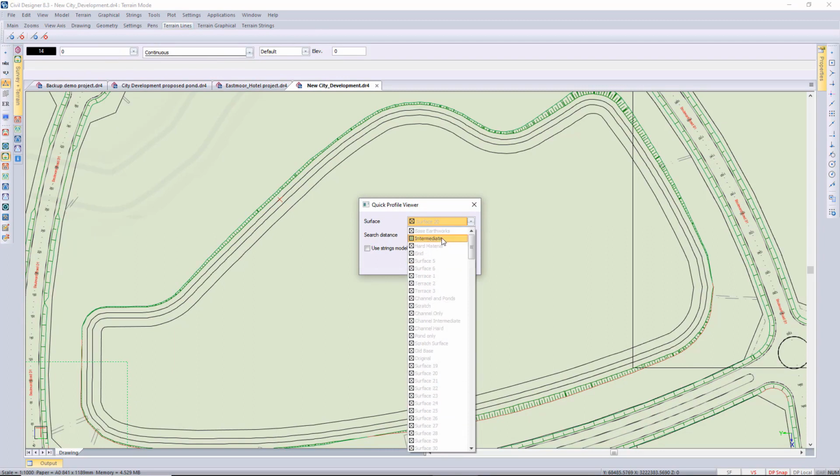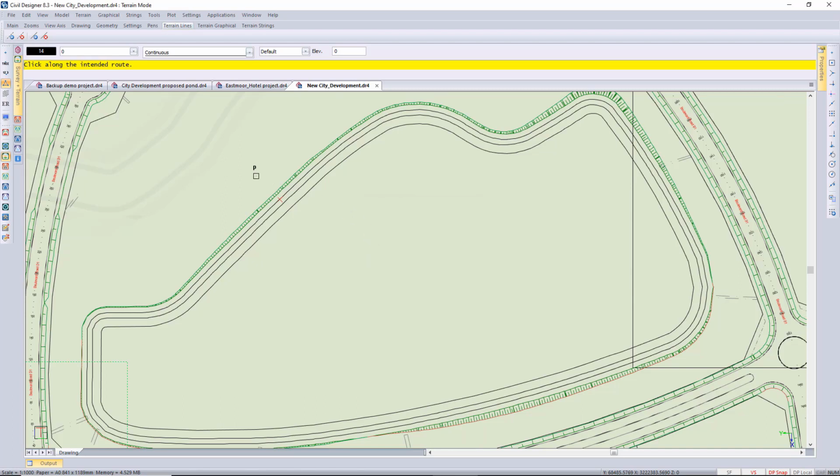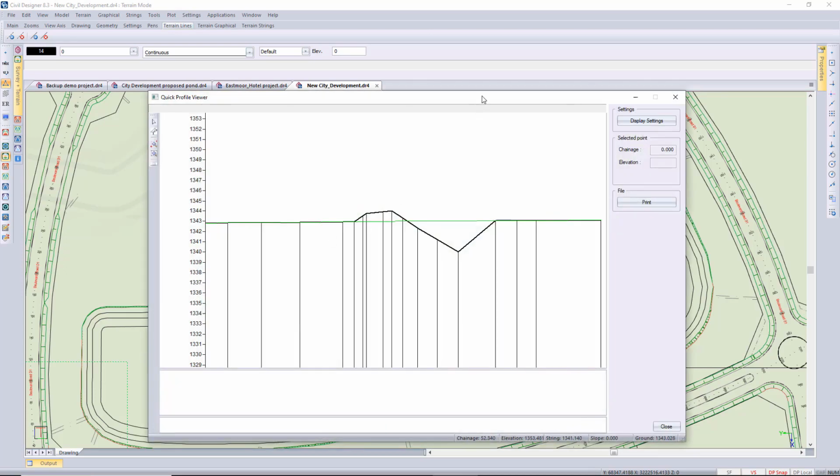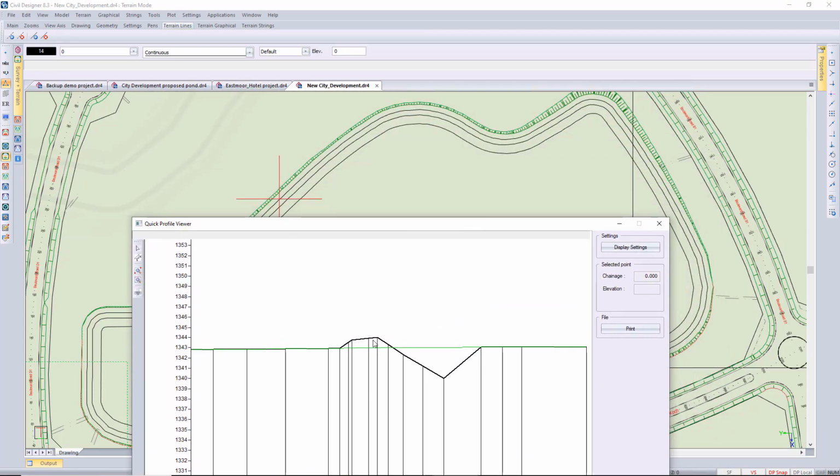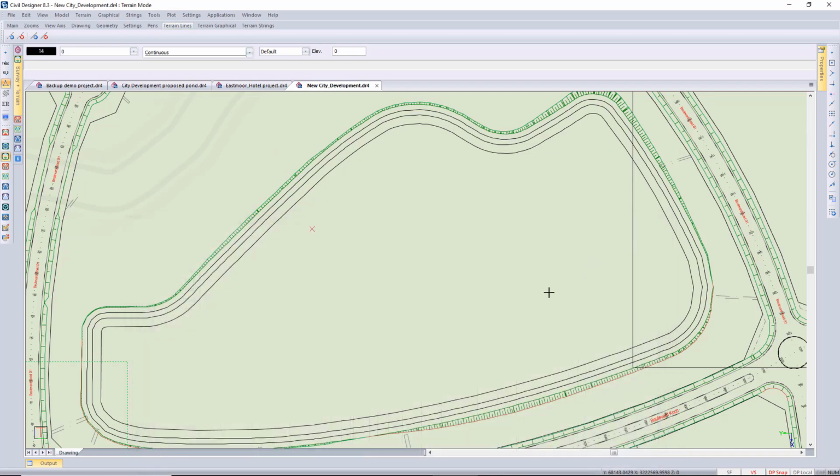For the DTM interpolation, we're using the string, so the terrain string model to interpolate your start and end points, so you can draw any kind of path. And then if I just move this down, you can see the crosshair, that profile through the dam wall. At the moment, after it goes to that inside string, it's just tying into the DTM.